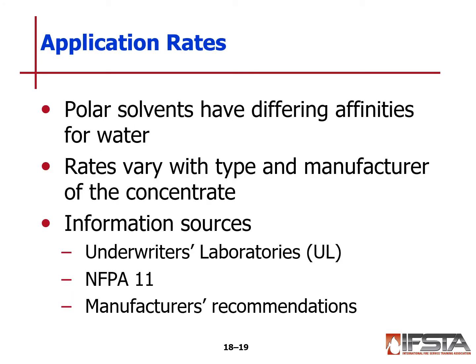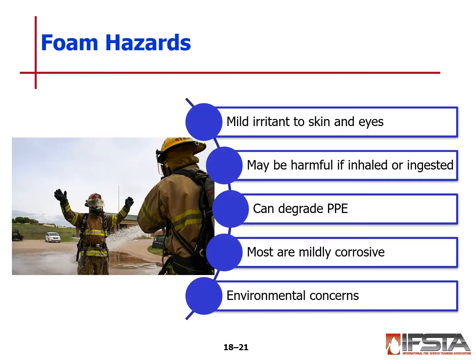Rates of application: polar solvents have differing affinities for water. The rates vary with the type and the manufacturer of the concentrate. Information sources include UL, or Underwriters Laboratories, NFPA 11, and probably more importantly, the manufacturer's recommendations on the application rates.